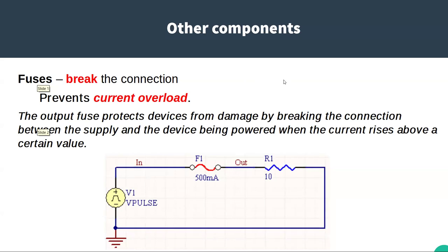Okay, we have fuses, and they're there to protect the circuit. So in the case of a current overload, the fuse will open up. Kind of like a circuit breaker, except the circuit breaker is resettable. The fuse, when it opens up, the actual element in there melts or fuses. So you have to replace it, like Dan had to do on his solar panels.